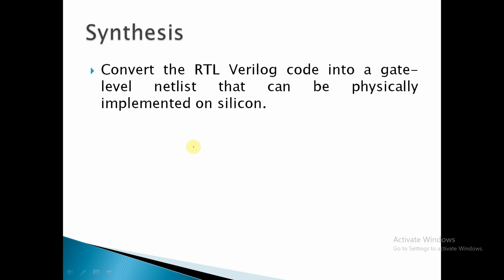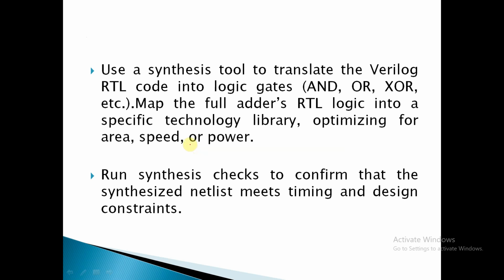So that is meant by synthesis. We are going to use synthesis tools that will convert Verilog RTL code into logic gates like AND, OR, XOR. In this example, we are converting the full adder's RTL logic into a specific technology library, and running synthesis checks to confirm that the synthesis netlist meets the timing and design constraints.